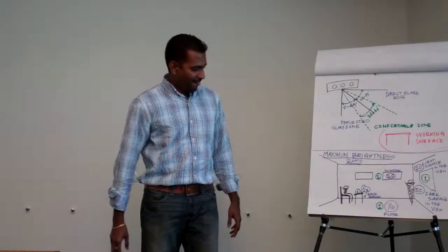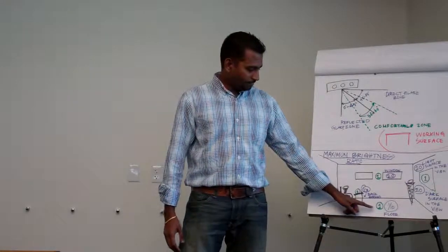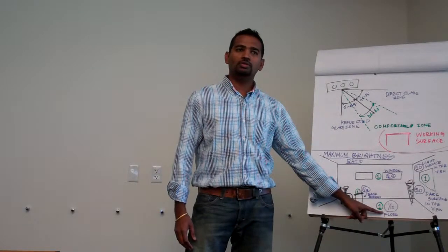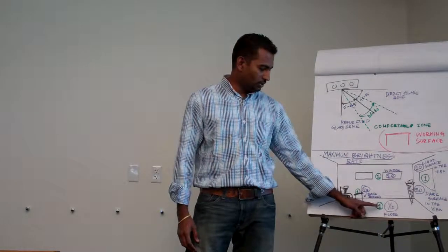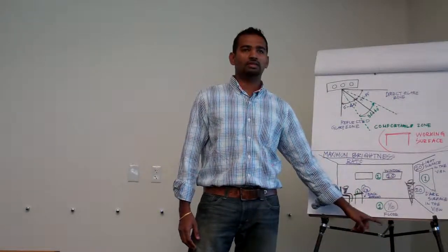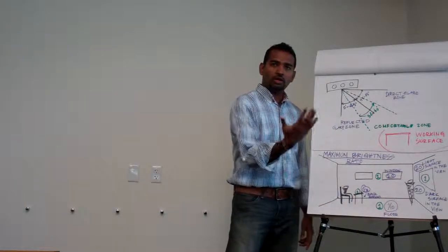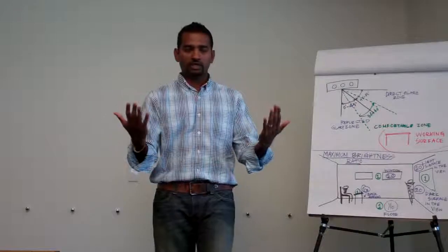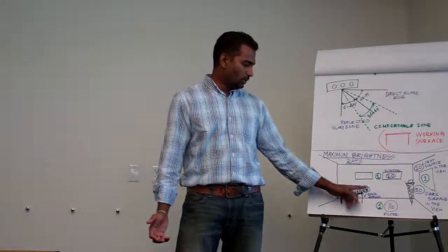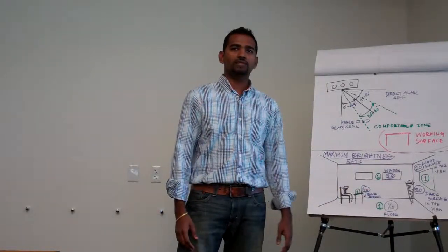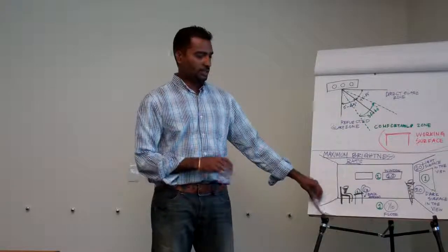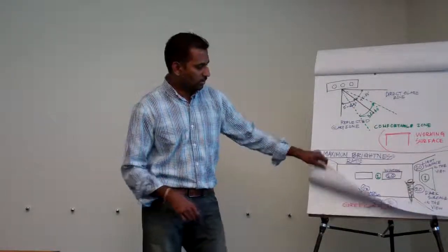Likewise, you don't want the floor to be too bright, so the ratio is 1 to 1/10. And likewise, the immediate surrounding around your work surface should be 1 to 1/3. This will be more understandable as I show an example. I'm going to run through this quick.